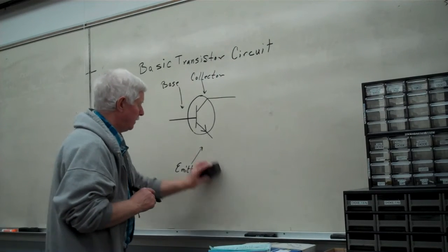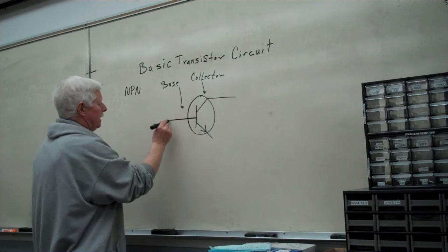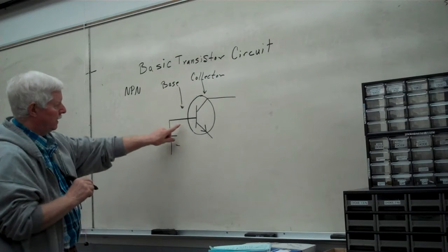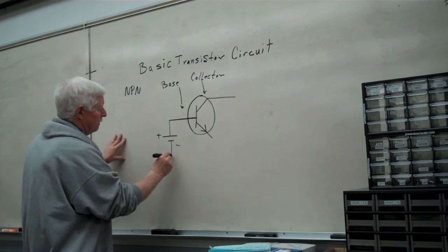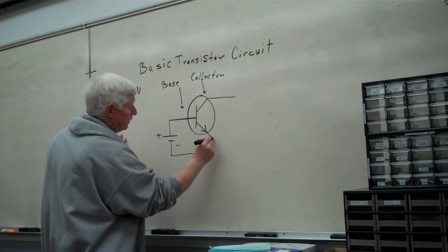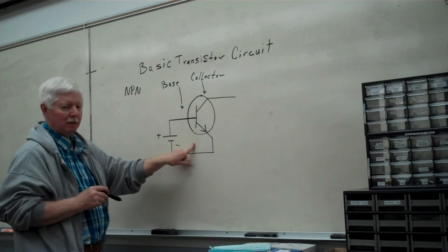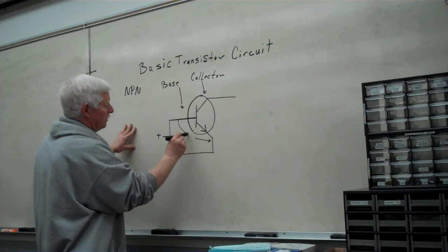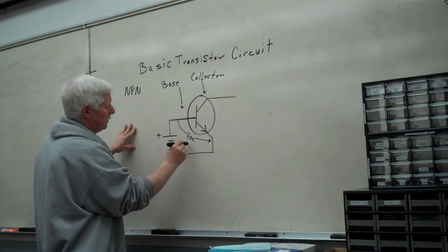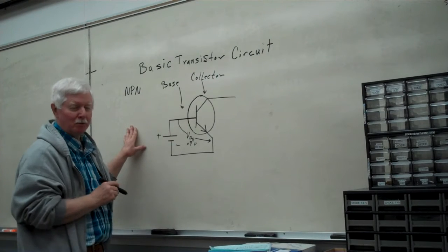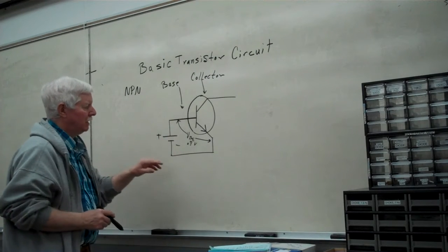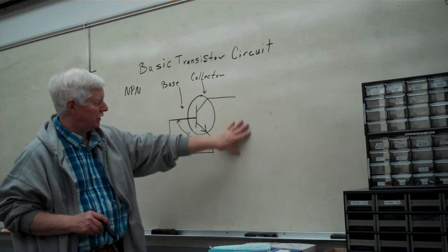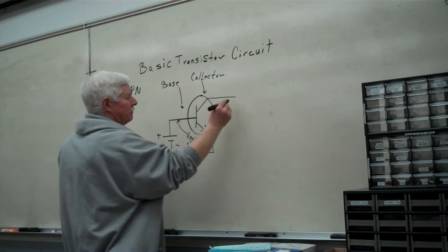In the first example then, we know that we had a positive voltage tied into the base and a negative part of the battery that connects down into the emitter. Know that current will begin to flow as soon as we have what's known as the base to emitter voltage of 0.7 volts. As soon as that occurs, the current can now go through this device. Let's connect in our collector supply.